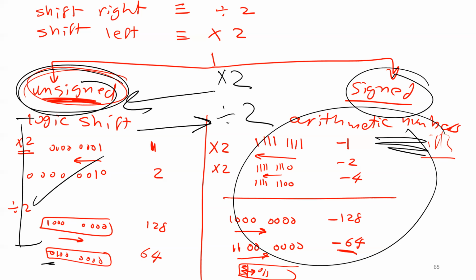So we can figure out what 5 times the number is by using logic shifts and having that number still. Shifts are much more efficient than multiplication or division instructions. The operation, because we're not doing anything, you just shift the bits. You get what I'm saying? So it's much more efficient than the operation done by multiplication and division instructions.